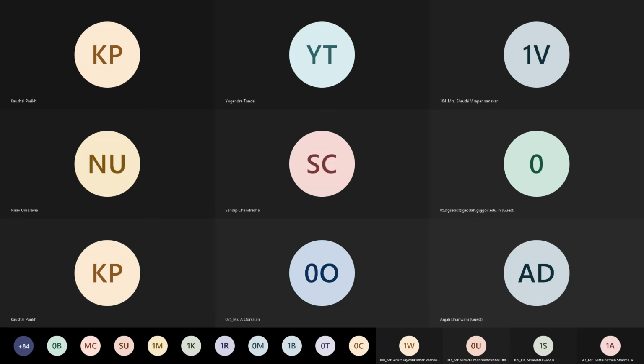When you are designing any kind of cross section, maybe a beam, maybe a column, your reinforcement and the concrete will contribute to the strength. Finally, through the jacketing, you are increasing the cross section. You are providing more reinforcement and more concrete. Definitely the strength will increase.